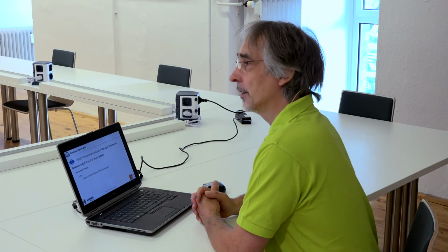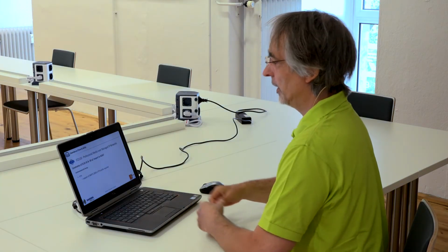AES67 devices. While AES67 requires the PTP default profile to be supported, AES has also defined an AES67 media profile for PTP. And when we look at this AES67 PTP media profile and the SMPTE 2059 profile, we see a very good overlap between these 2 profiles. So in other words, whenever we want to bring AES67 devices into a 2110 environment, the overlap between the 2059 profile and the AES67 PTP media profile can be used to make these devices interoperate nicely and in a synchronized manner. However, we have observed through past interop events that most AES67 devices support the 2059 profile anyway, so natively.